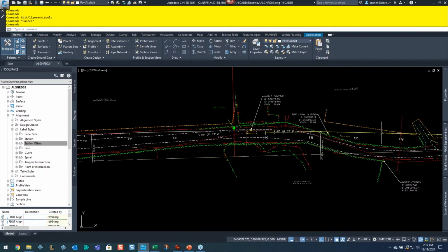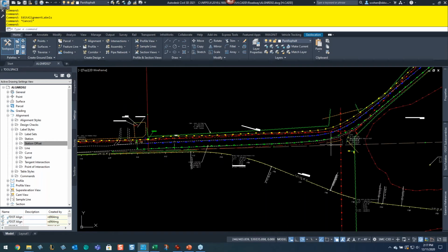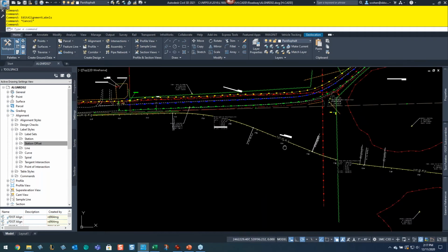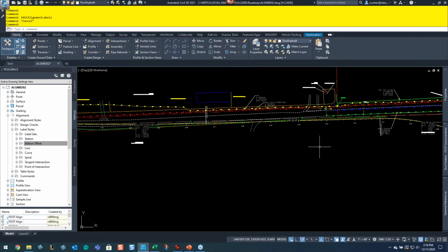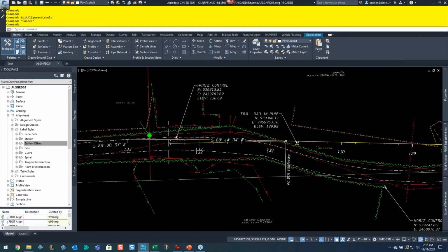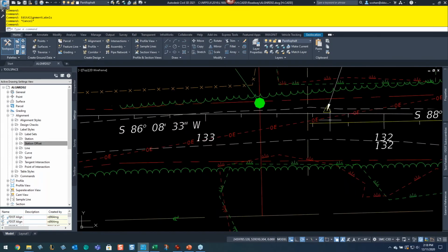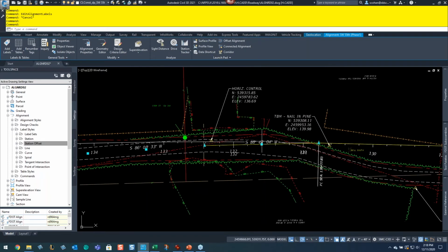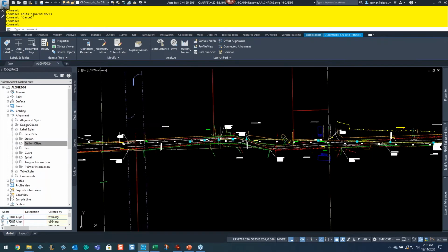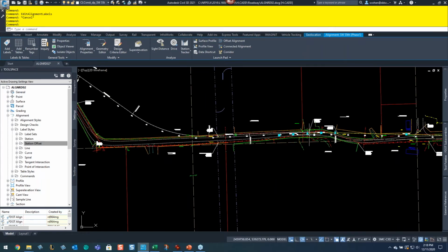We have a couple of ponds here in phase one, because as you can see, we're off of the existing road. Here's the existing road. So we're off of it here, and we have this pond in this location basically to compensate for the relocation of the road. But we tied back into existing because the money took us close to this area. This is the alignment of phase one. But because I knew there was going to be a second phase that was going to do the entire road all the way up through here, I did some alignment past that so I could at least tie into it.